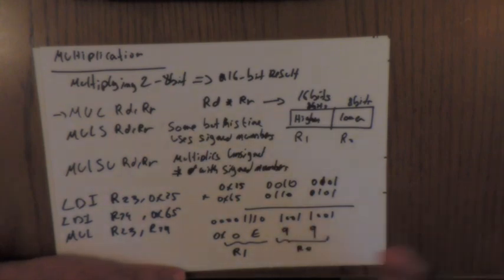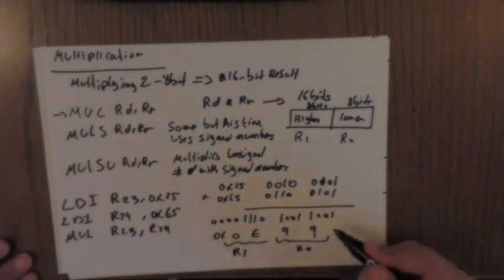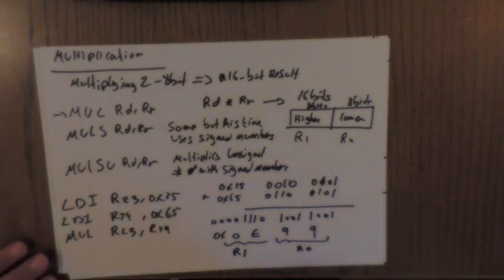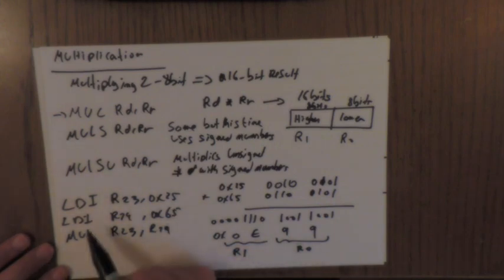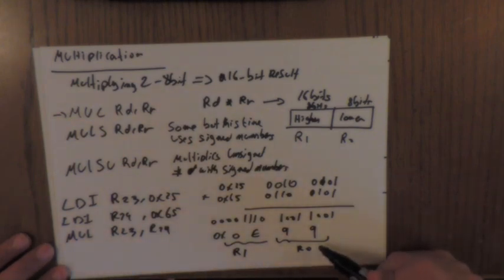These are the lower bits and this is the higher bits. So now I can do any instruction to work with them. If I want to add those numbers, I now have them in R0 and R1. So when multiplying two numbers using an AVR microcontroller, the multiplication instruction will store the lower byte in R0 and the higher byte in R1.